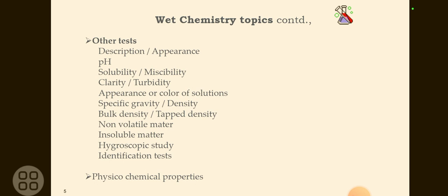So if you know that the material is hygroscopic, you will take care with different packaging conditions. Like that, you will use a triple laminated pack, or an LDPE pack under a triple laminated pack under a nitrogen atmosphere with a closed sealed HDPE drum. You will pack the material in such a condition that it should not absorb moisture. If your compound is not hygroscopic, those packing conditions are not required. Simply you will pack in LDPE and directly in an HDPE drum, or maybe in a triple laminated pack. There nitrogen purging is not required. So this is the characteristic property to know what type of packaging or what type of export conditions you have to maintain during the shipment of your compound.